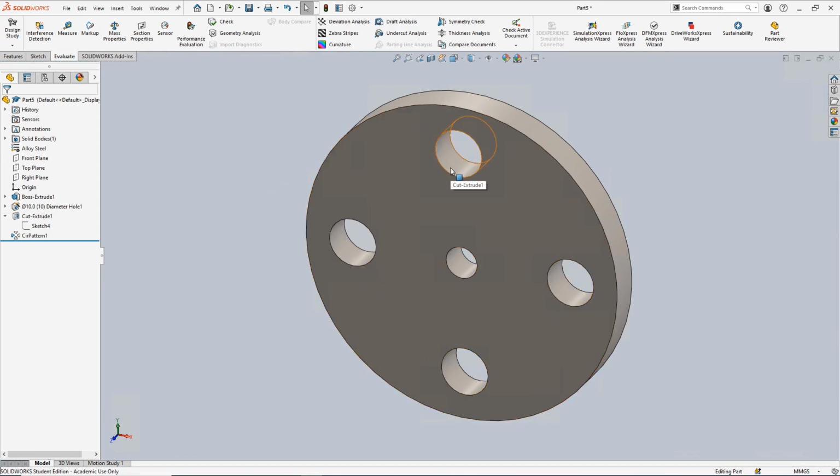So if I remove material from larger diameter, we decrease the moments of inertia. If we remove from closer to the center, we will have greater mass moments of inertia. So using this technique, you can control the mass and moments of inertia to design a certain flywheel.